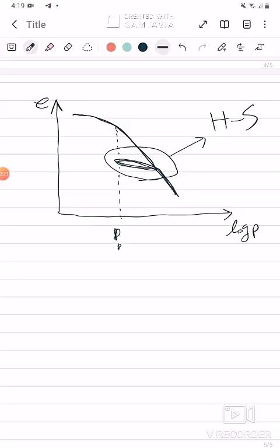So we can conclude that in modeling with Plaxis, when the situation is not in failure mode, the behavior of HS is more realistic than MC, but in failure mode, both of them are the same.